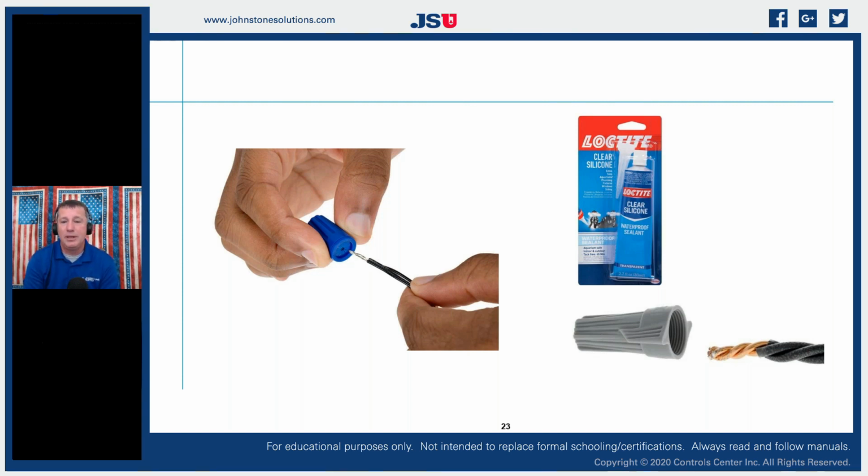communicating wiring. And so the systems that have reused the existing line sets and reused existing control wire, because you can, a lot of the manuals will allow you to use solid conductor communicating wire, and they can allow you to use existing tubing line sets. They're required to be flushed out, and the control wire is required to be in good standard.